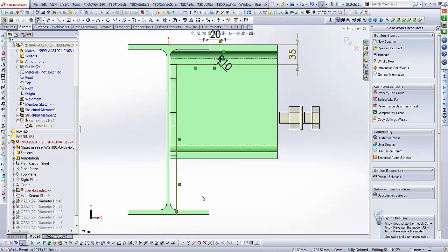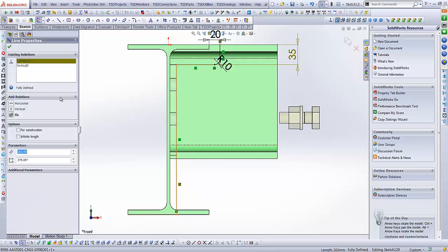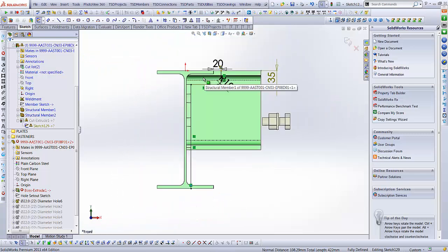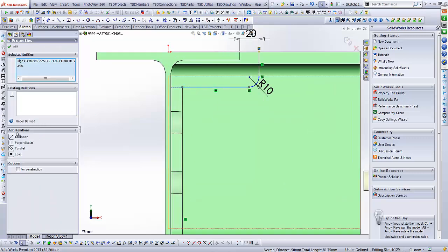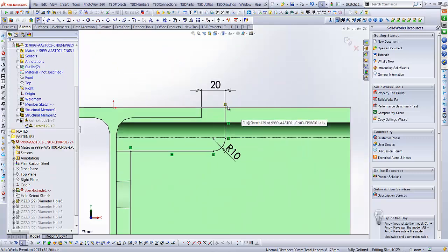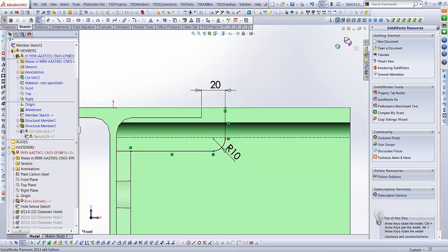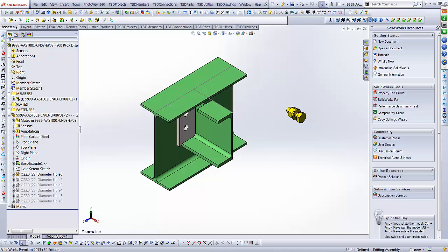I don't like deleting things unless I necessarily have to. This cut itself goes all the way down to this beam. Okay, we'll just make that. The collinear relationship for this edge is obviously related to the plate, so we'll just make that collinear. And the top of this is related to where the plate is, so we'll just make that collinear. And we'll just make sure that everything else is fixed, so I'm just fixing that point on. So the whole cut is now justified. There is no error in it, and it's fully defined.